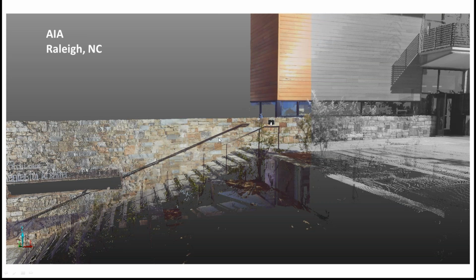All right. In the screenshot, you can see, and I'll make a little marker here. So that was the location of one of the scans. It's a little 3D model of the scanner itself. And one thing you'll notice, the closer you are to the scanner, the higher the density of the points. The nature of laser scanning is that we're mostly concerned about density. When we talk about resolution or quality and things like that, we're talking about the spacing between each point. And the closer the objects are to the scanner, the higher the density of the points. And if you look over to the left, you'll see the further we go out, the higher that spacing is.